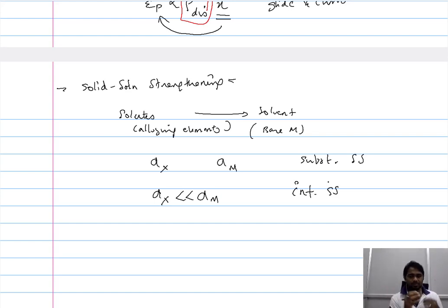So we want to strengthen the material, or enhance the creep life of the material, by introducing solutes. And the positions of the solutes, or rather how these solutes dissolve in the base metal, depends on one factor that governs it, which is the size of the atoms of the solute.